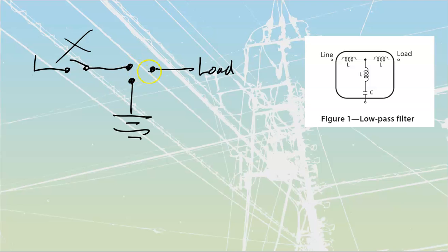The two main types are either the online, or the offline, or standby. The standby ones do have an interruption because power fails, they wait a little bit, then they transition right over to feed my load. They are cheaper because they don't see continuous current flow. An online type actually acts almost like a VFD, where I'm going to take this in and convert it into DC. Let me see if I can draw that a little bit better.